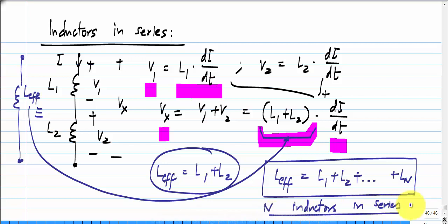Okay. Now these are all elementary results. What I want to emphasize is that we start from the basics, that is KCL or KVL. Here, in case of series combination, Kirchhoff's current law tells us that the same current flows through all the elements. Kirchhoff's voltage law tells us that the voltage across the ends of the combination equals the sum of individual voltages. Then we combine these consequences from Kirchhoff's current law and Kirchhoff's voltage law with the IV relationship for each element and deduce the nature of the series combination.